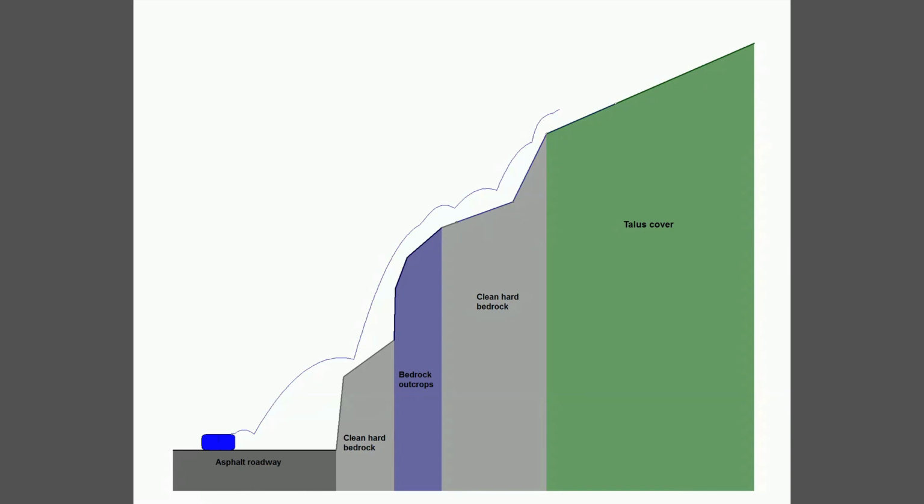If you have a slope that has the potential for outward-facing dipping slopes that effectively become ski jumps for the boulder, and you'll notice how that boulder tumbled down and occasionally hit something and bounced outwards. It's the outward velocity imparted by those slopes that is dangerous, because that is what pushes the boulder out into the highway or whatever you have below you.